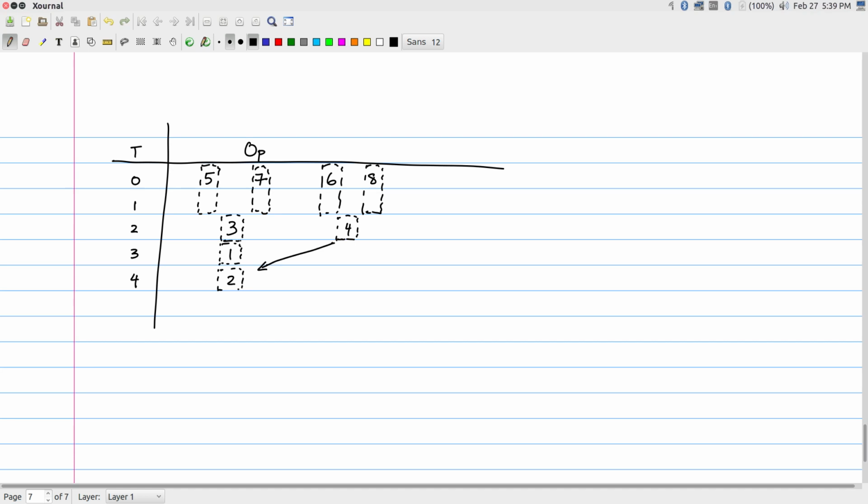Okay, so can I come up with something better? How do I improve upon it? How do I modify this? Those are the questions that we are going to address next. Okay, so we'll stop here for now. Tomorrow we'll continue with this, look at the basics of as soon as possible scheduling, switch over to as late as possible scheduling, how we can move that around, and also see what kind of changes we need to make to the original graph so that it can be scheduled within 4 time steps, and then we can actually meet our constraints. Okay, all right.